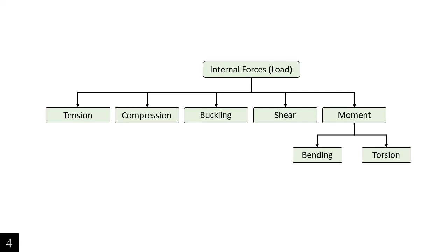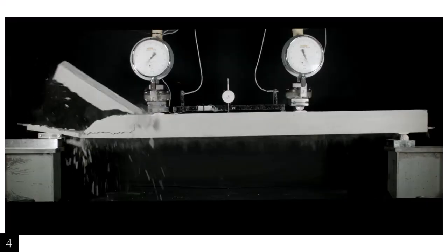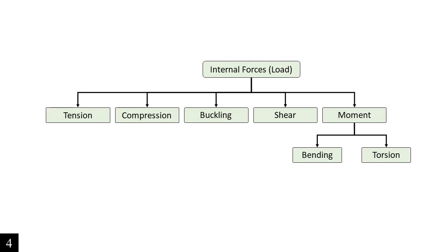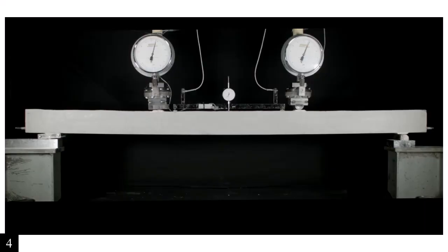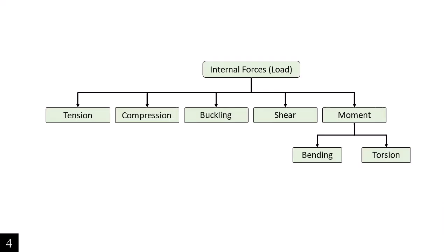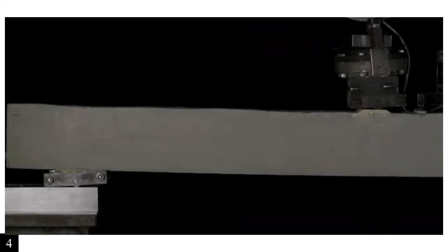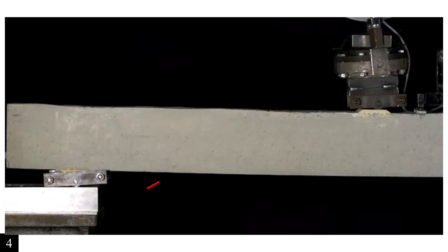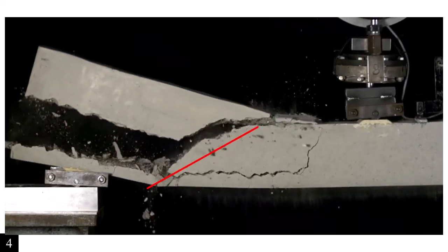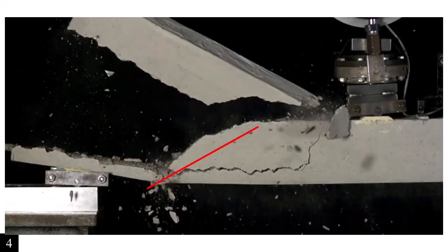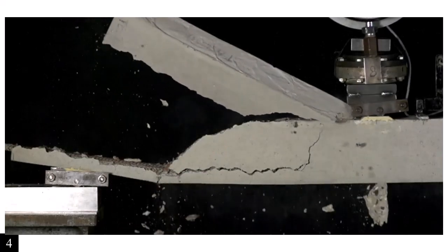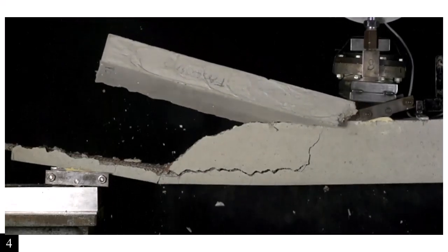First of all, shear force failure is something that happens very fast, suddenly, and there's no cracking, there's no bending at all, and usually that one is unpredictable. That one happened very quickly, so it is a shear force. And also, if you take a look at the video, you will see that there is a diagonal cut in the beam that is usually due to the shear force.